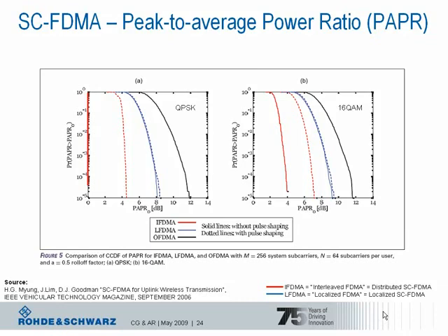Just the defined in-channel requirements, for example modulation quality measured with the EVM, and out-of-channel requirements, adjacent channel leakage power ratio or spectrum emission mask, need to be passed by the transmitter design. In this simulation, a root raised cosine filter was used with a rolloff factor of 0.5.